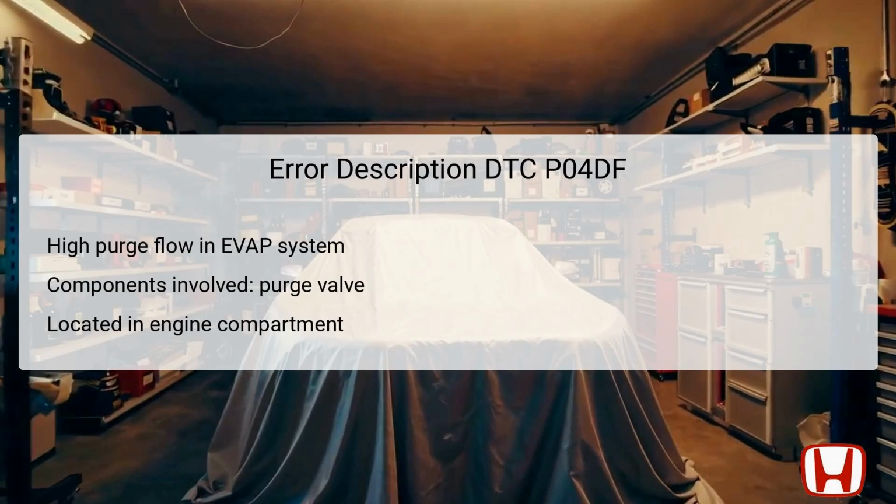The purge valve opens when the engine is running to allow vapors to enter the combustion chamber, thus preventing excess emissions from being released into the atmosphere. A malfunction in this component can lead to issues such as failed emissions tests and decreased fuel efficiency. Understanding the function and location of the purge valve is critical as we troubleshoot this DTC effectively.